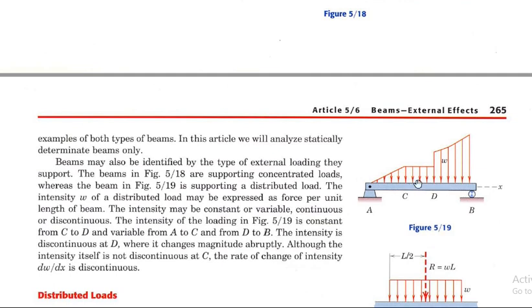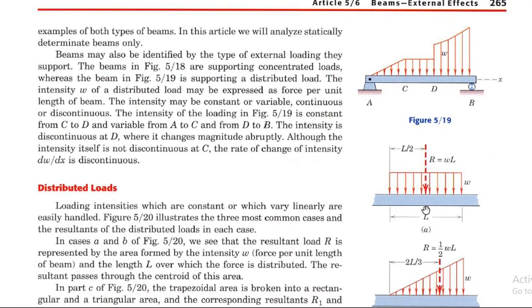Then this diagram illustrates the load distribution on a beam. It can be constant, or varying in a regular pattern or an irregular pattern. Then for distributed loads, we have to solve like this one. L is the complete length of the beam, and the weight of the beam or a uniform load will be distributed likewise, acting at the length of L by 2.